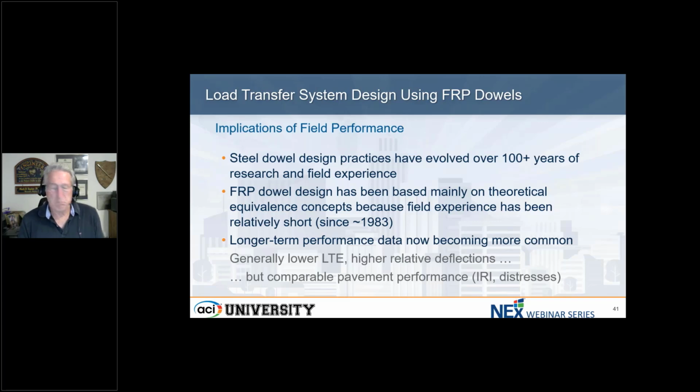So that's what research suggests. But we need to look at field performance, because our steel dowels have evolved over 100 years of research and field experience. And FRP dowel design, until recently, has been mainly based on theoretical equivalence concepts like we've been talking about, because we haven't had much field experience.